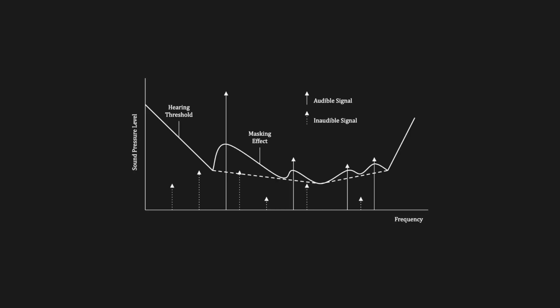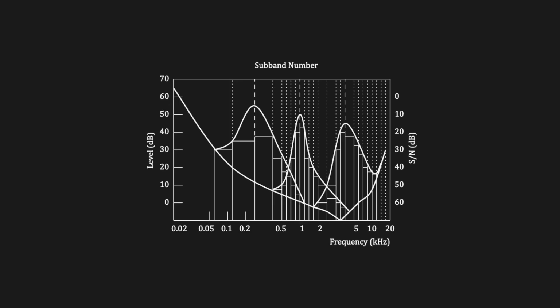Bits are assigned according to a priority system. More bits go to subbands with stronger or more audible sounds, above the masking curve, while fewer bits go to quieter, less audible parts. Sounds that fall below the masking threshold can still be coded, but only with lower priority. In all cases, the quantization noise is kept below the combined masking curve so that it remains inaudible to the listener.